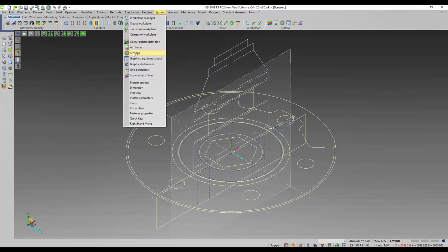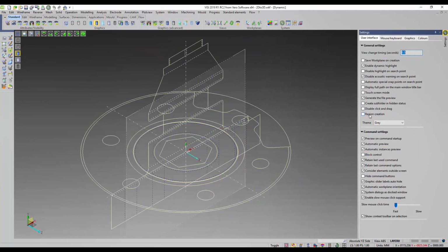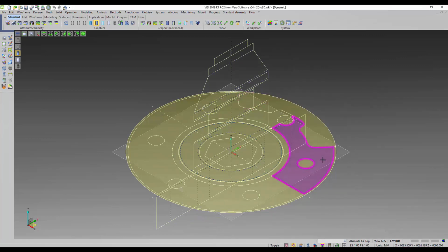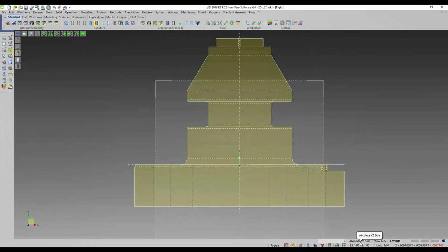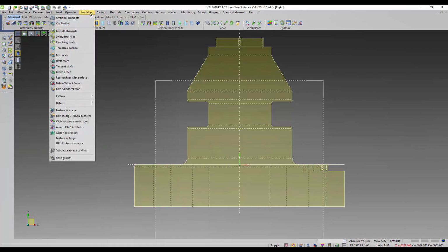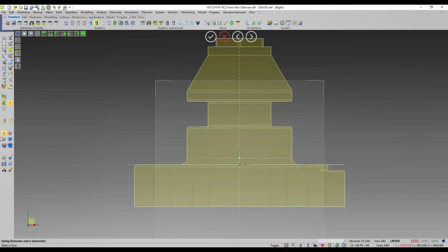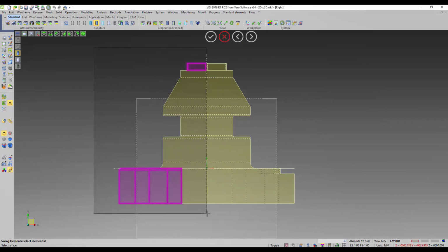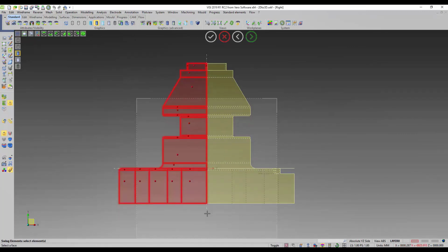Keep in mind, guys, under the system settings, region creation is on by default. Now, if you are opening up a huge design file, you want to make sure that's turned off. Obviously, you're going to have multiple plot views in there sometimes, and that can cause some region creation to occur. If you do open one of those big files, in the lower left-hand corner should be the ability to hit ESC and stop that region creation. Especially on those viewer computers, we'll have to make sure that's off.